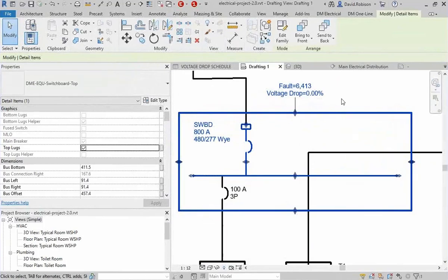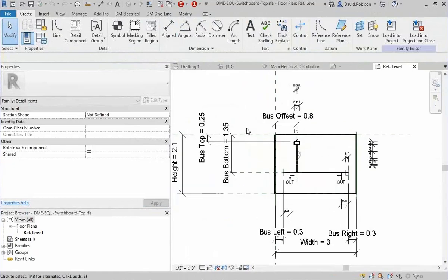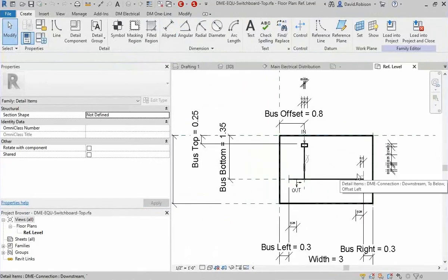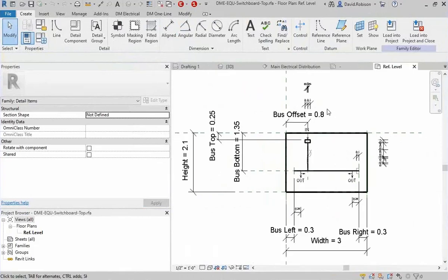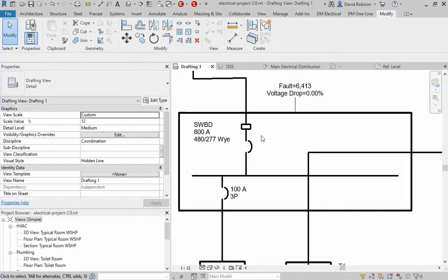The families, again, are also just standard Revit families. If we click Edit Family, here's the family that we've created. Our families, we've worked a little bit on them to make them play nicely, so you can adjust some of them so that the feeder, so the breaker adjusts the main breaker, the disconnect shows a breaker, a fuse switch as appropriate.